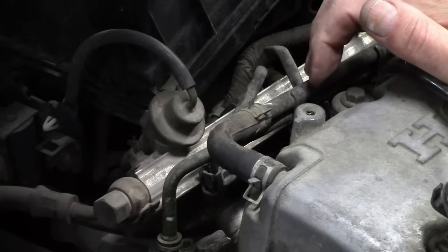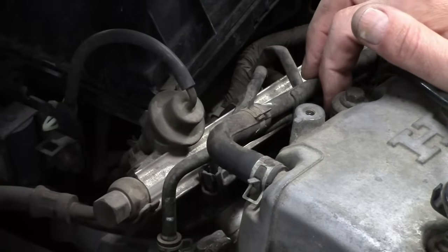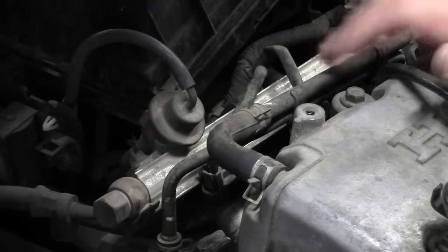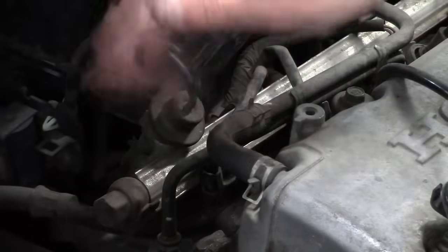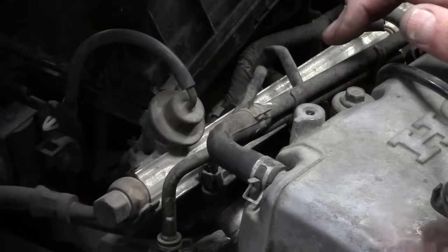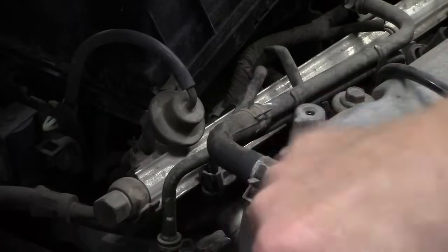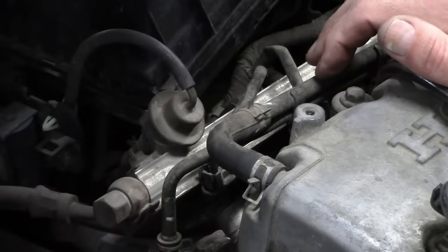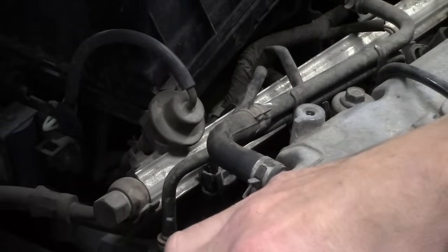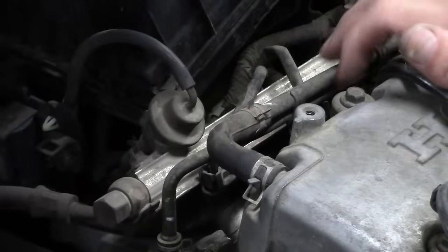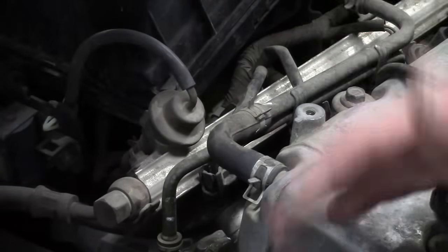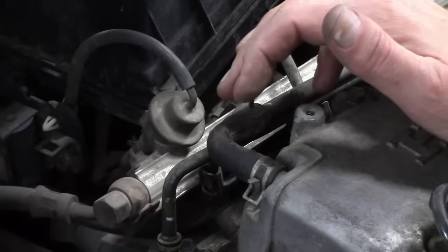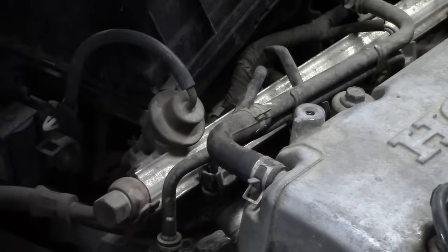I was not able to locate a crankshaft position sensor on the engine. Typically that's going to be near the crankshaft pulley, or also somewhere near the transmission using the drive plate as the reluctor wheel. I was not able to find anything on the engine, so I'm assuming most likely it's internal with the distributor. There was not much that I could do at that point. Of course, I tried banging on it a little bit, hoping to get it to work. Sometimes with a bad sensor, you can tap it with a screwdriver or something. Had no luck with that, and I told the kid, well, this is as far as I can go, but I believe that's where our issue is. So that's where we are now.